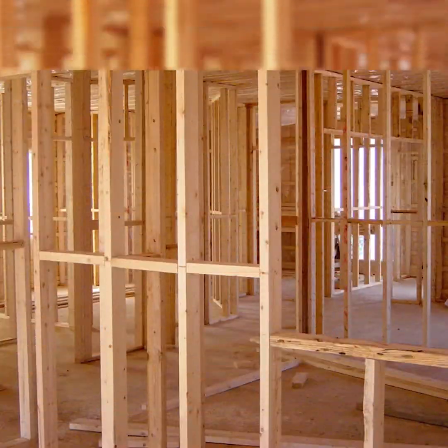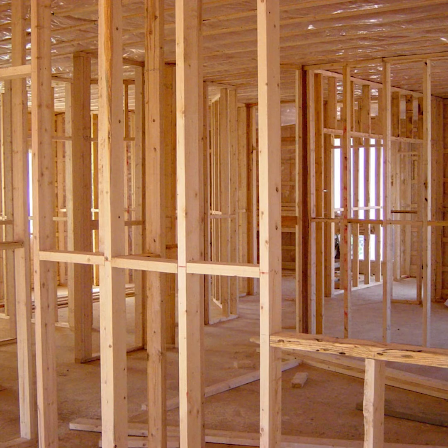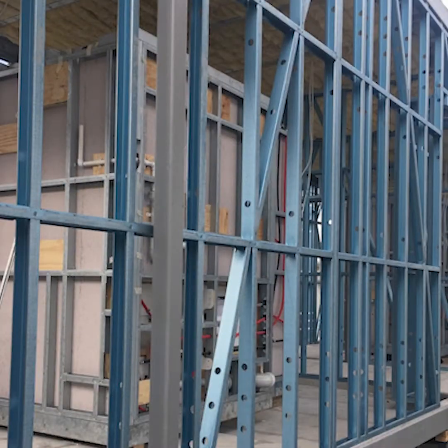Studs. A stud is a vertical framing member which forms part of a wall or a partition. Also known as wall studs, they are a fundamental component of frame construction and are typically made of timber but can also be steel. Studs come in different sizes. The minimum size that can be used in a specific place is specified by the engineer. Generally, they are 90 mm wide by 35 mm thick and 90 mm wide by 45 mm thick. But they can go up to 240 mm wide by 45 mm thick for passive houses. This is because you need more insulation in a passive house wall, so the wall needs to be wider.